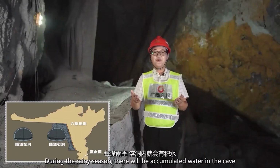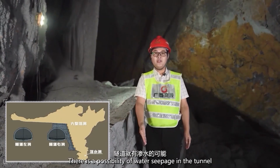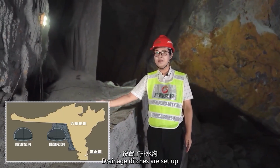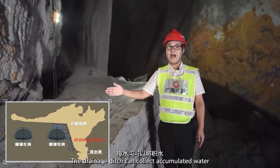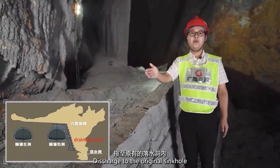During the rainy season, there will be accumulated water in the cave. There is a possibility of water seepage in the tunnel, so drainage ditches are set up in this position. The drainage ditch can collect accumulated water and discharge it from top to bottom to the original sinkhole.